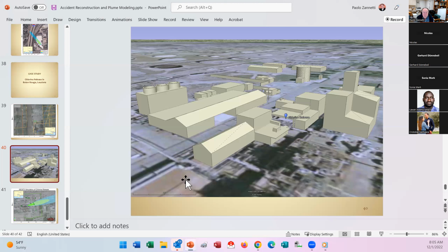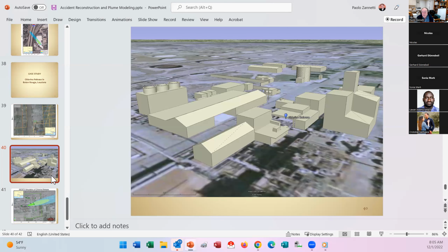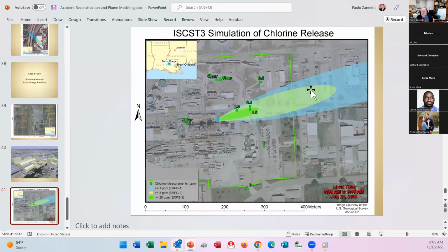So I thought about it, and I decided, well, I can still apply a Gaussian plume model with some uncertainty, but still. My conclusion was that the effect of the buildings is more dispersion. More dispersion means more opening up of the plume, and more opening up of the plume means lower concentration. So by not using CFD, I'm overestimating the concentration. And I thought, that's fine.